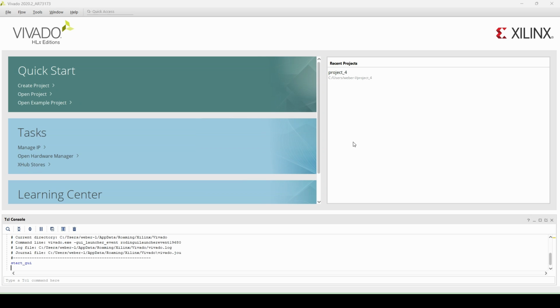Xilinx FPGA has a built-in bootloader mechanism and warm boot vector in the bitstream. The multi-boot feature enables the FPGA to selectively load the bitstream from a specified address in the flash memory. We will take a look at the details in a moment.